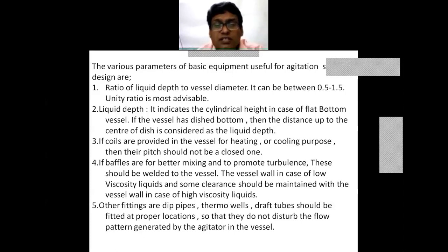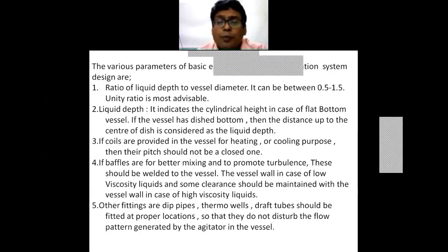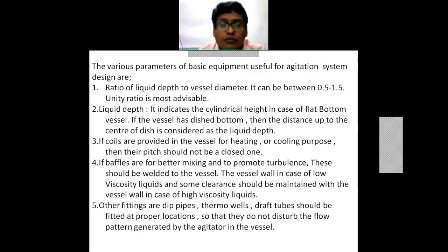Then the baffles are also provided for better mixing and to promote turbulence. They should be welded to the vessel wall in the case of low viscosity liquids. That is, generally if the viscosities are low, then we provide the baffles welded to the wall, and for high viscosity liquids some clearance is maintained between the vessel wall and the baffle.